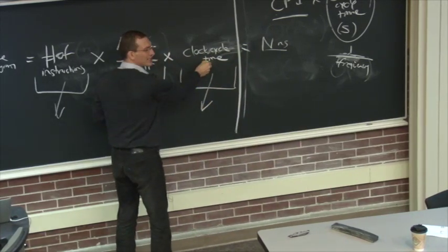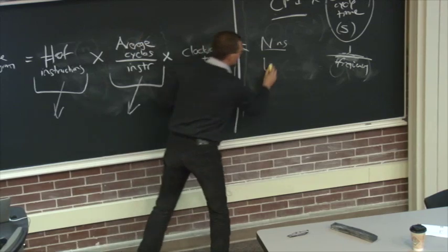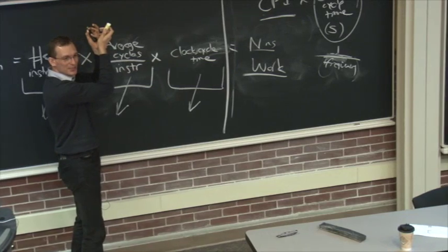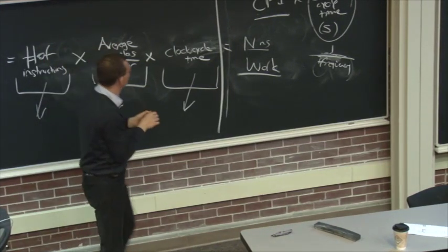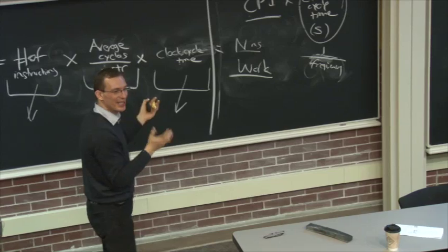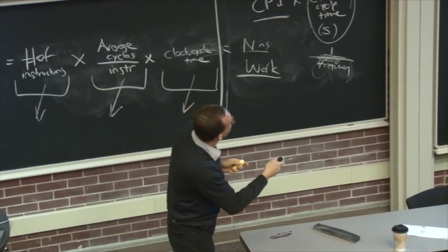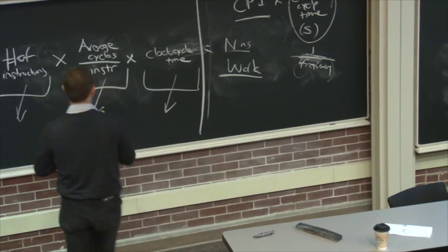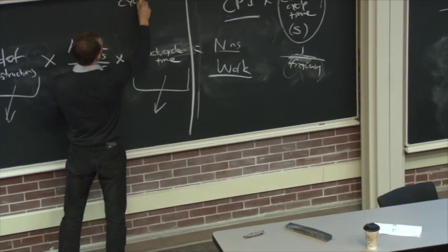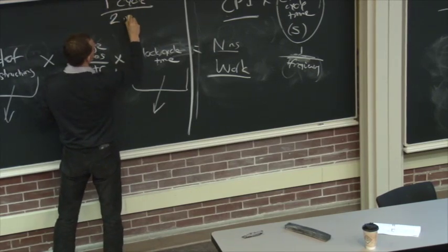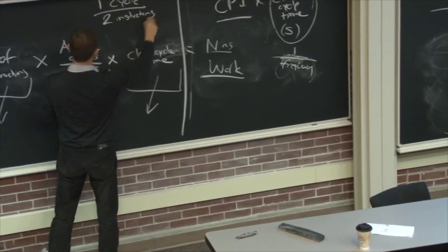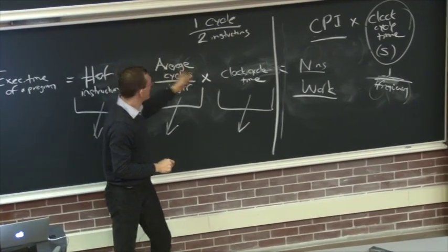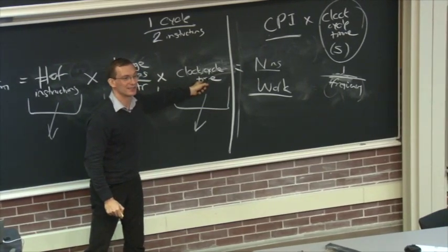Because if you reduce the clock cycle time, because you have a fixed amount of work to finish an instruction, you're usually increasing cycles per instruction, right? But you can get away from this. As an architect, you can be creative, right? You can say, oh, why not process multiple instructions at the same time? If you do multiple instructions, basically you're amortizing the same cycle. Let's say you're doing 2 instructions. Well, it's nice, right? Your average cycles per instruction goes down. Maybe you don't change the clock cycle time if you do that.